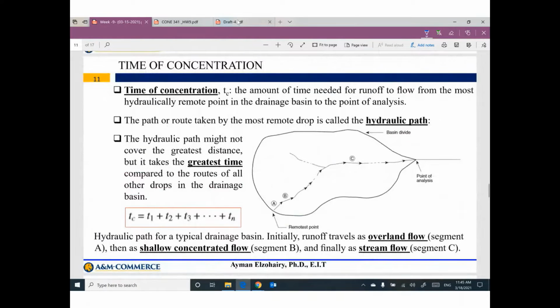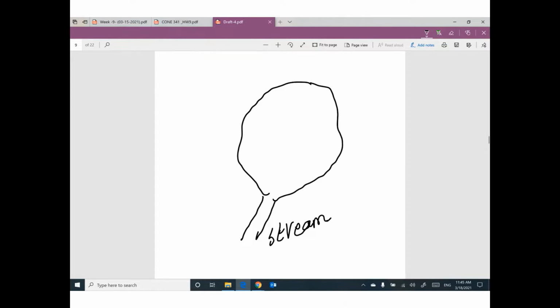Okay. One more thing I covered last meeting, and I will repeat this question one more time. We have a drainage area served by this stream. My question is, once the rainfall starts, one second after the start of the rainfall, do you think we can reach the maximum flow, or we can call it peak flow, in the stream just after the start of the rainfall, or do we need to wait a little bit? The answer last meeting: we need to wait a little bit.